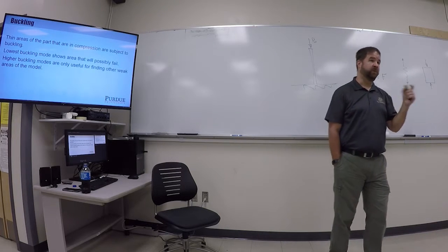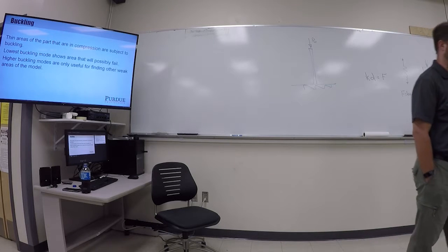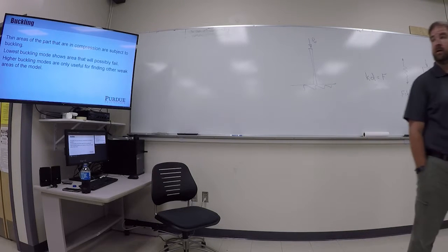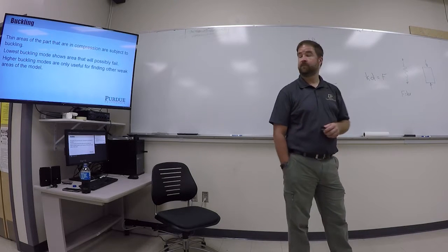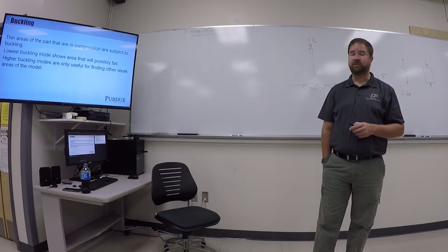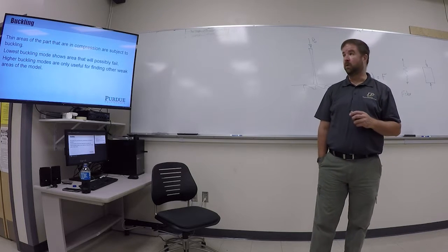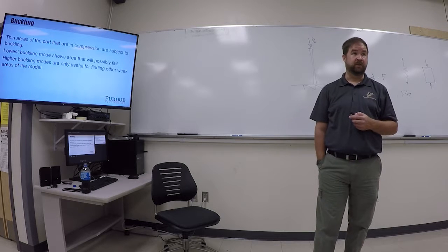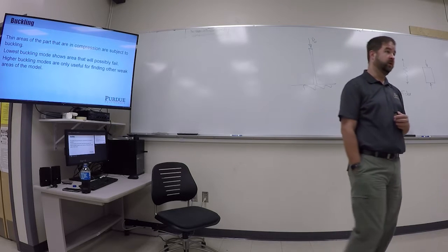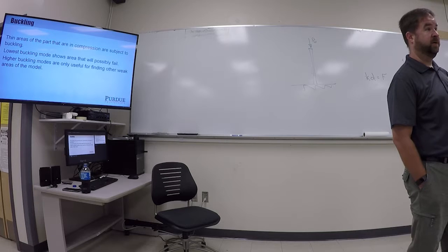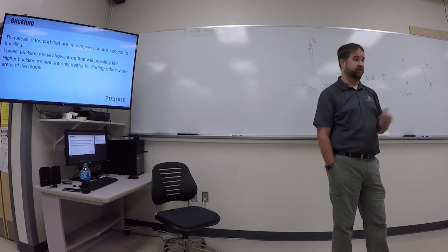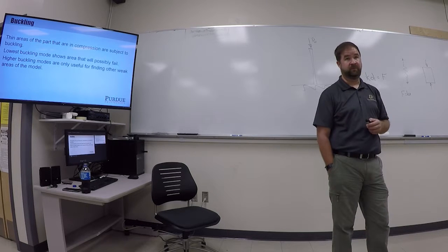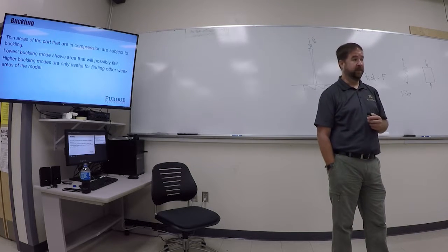So you get multiple modal outputs, multiple buckling modes can be output, but the most useful one is the first one because that's where it's going to actually fail. And so you can find the weak areas of your model, or if you're designing tank cars that are going to be steam cleaned, you could try to reinforce the car such that if somebody did close it overnight, it could withstand the vacuum on the inside and the atmospheric pressure on the outside. We could design the tank car to handle that.